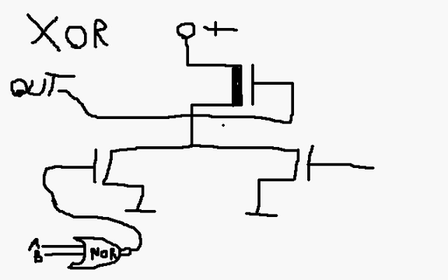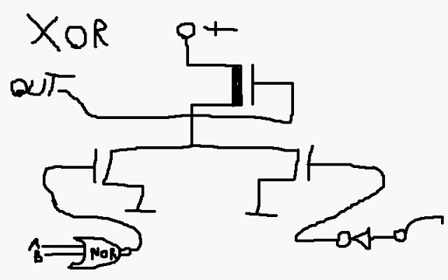And on the other side, what it does is it uses the input from its NAND gate. So basically, over here, on each XOR gate inside the 6502, there is an inverter like that. And then there is, just as it borrows the NOR gate on this side, it borrows the output from one of its own NAND gates.